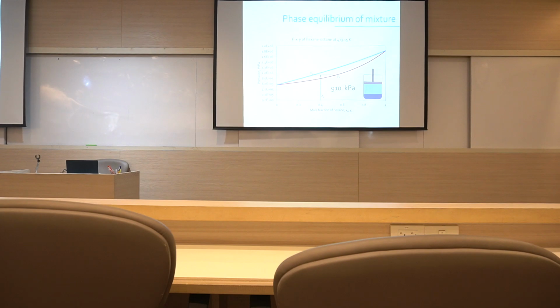However, if we talk about the composition in liquid and vapor phases, these two phases will have different compositions. X1 refers to the mole fraction of hexane in the liquid phase. So we can read that from the diagram. From that point, it's about 33%, something like that. So the liquid phase here, lying at the bottom of your vessel, has 30% hexane in it, and the rest, 70% in the liquid, is octane.